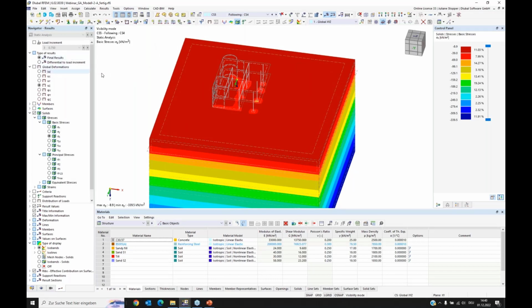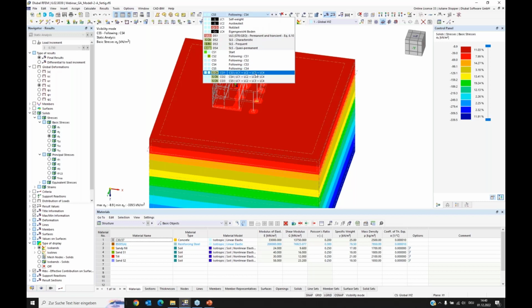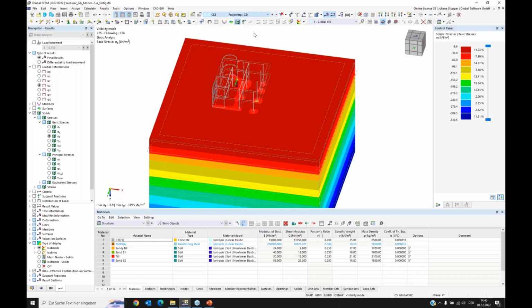differential results only for stresses of the building, because now we know that in our whole structure, the result of the stresses of the soil self-weight is considered. And if we check the differential result, only the result of the building, we can see the contact stresses from the structure. Therefore, I prepared load cases. This needs to be done for load combinations I prepared.